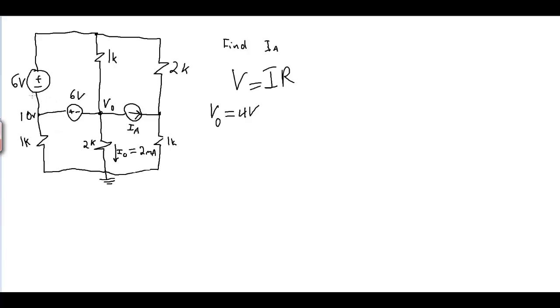And the same thing we have over here. So we can go from 10 to 16 volts up here. Oh, that's a 6. How do you know it goes up and not down? We know it goes up because of the polarity on the voltage source. This is the negative, the lower side, and this is the positive, the higher side. So this is going to be 16 and that's 10. Gotcha.